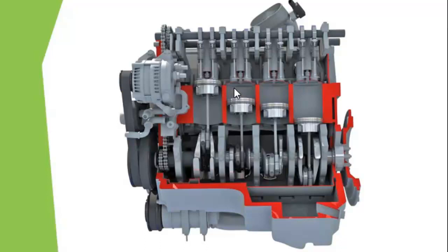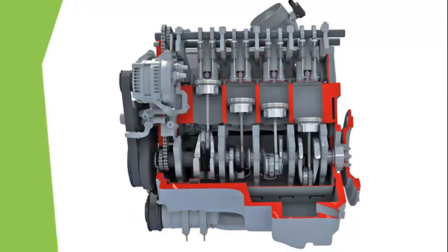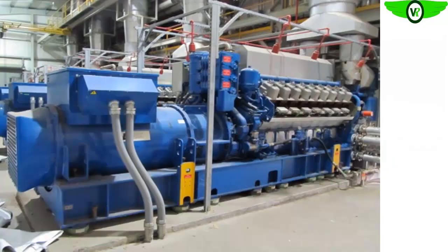Once it is ignited, that high energy combustion product forces the piston to move down. As it's moving down, that translational motion is converted into rotating mechanical motion by the crankshaft. At the other end of the crankshaft is where our alternator is coupled. So you see that the diesel engine's major function is to provide that rotating mechanical energy from the chemical energy that is contained either in the gas or in your diesel.